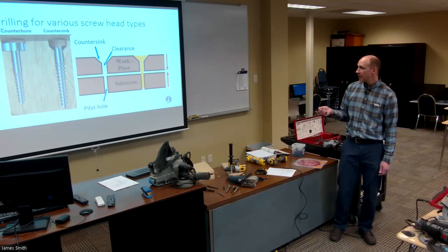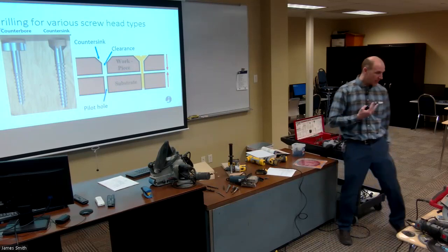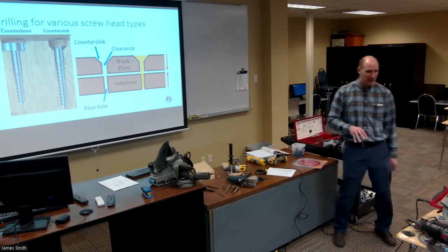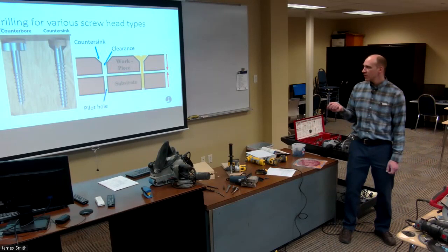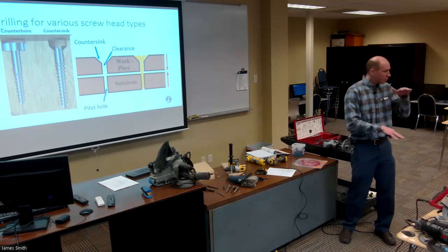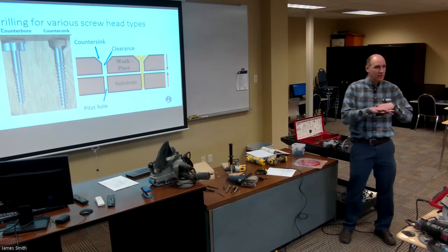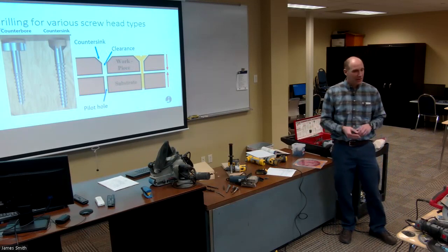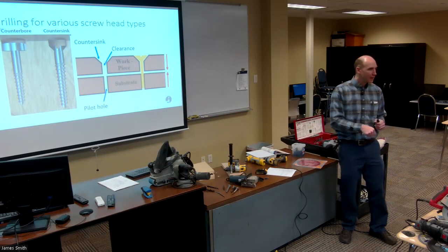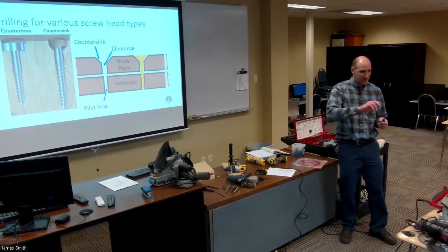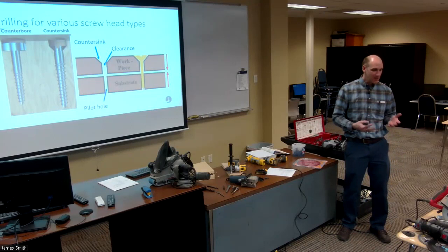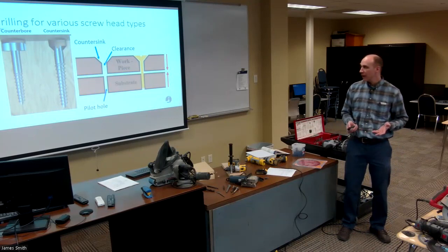But yeah, the other thing too that not many people think about, and at least sometimes it's hard to explain, is when you're drilling two boards that you want to suck up nice and tight with each other, and you're drilling oak. I think somebody was doing it in class the other day where they were trying to drive a screw into oak without drilling a pilot hole. Was that one of you guys? What happened? The head of the screw twisted off and snapped off. And so oak is hard enough that you have to drill a pilot hole first, okay?